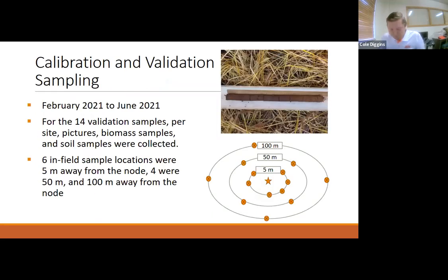So moving into that calibration and validation sampling I talked about. When doing our validation, we collected the soil volumetric water content the same way that we would have done during the calibration, but then during the validation looked at what our cosmic ray neutron probe and our Chrono Station was estimating the theta to be, and then compared that with the theta during our validation.